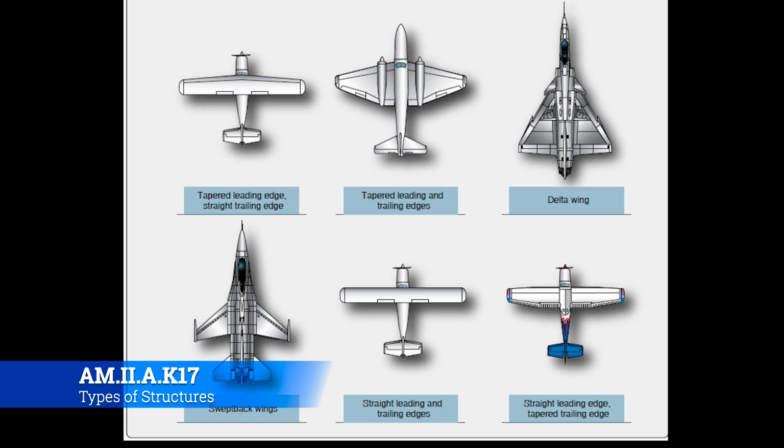Your sweepback wings, that's an F-16 on the bottom left. Notice that those wings are small, but the F-16 is basically a rocket ship. There's a huge engine that the pilot just sits in front of, and the wings, while they generate lift, you don't need that much wing out there because the lifting surface is going so much faster. So there's kind of an efficiency factor. If you look at a Predator drone, very small engine but humongous wings. An F-16, very big engine, small wings. That's simply because for every square inch of the F-16's wings, it's able to generate way more lift than a normal airplane because that engine is pushing the airplane through the air that much faster.